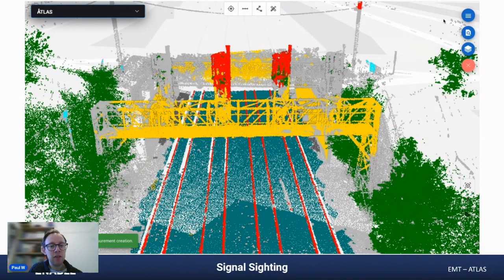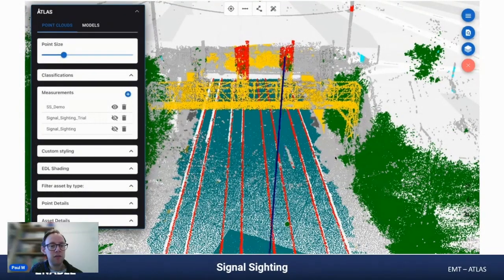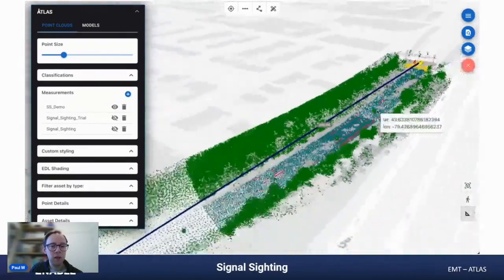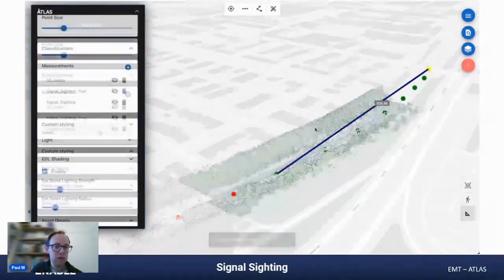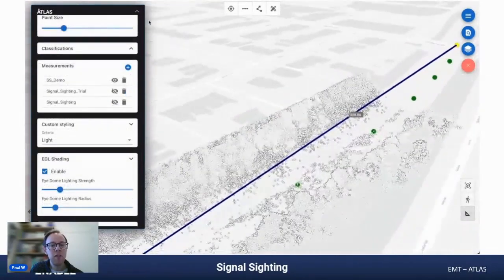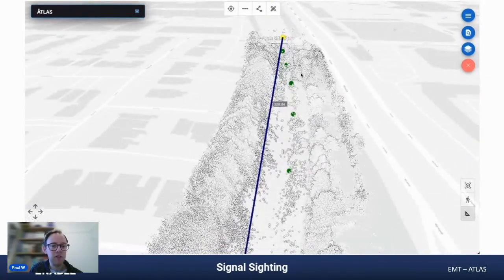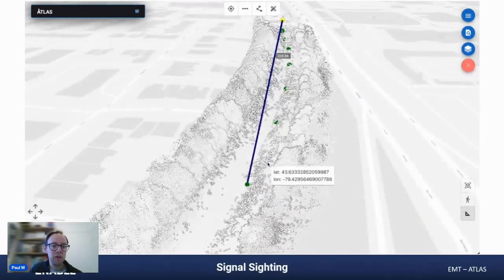After the calculations have been completed, the results are displayed, overlaid within the view. The maximum unobstructed line of sight is represented with a blue line, along with the source coordinates being color-coded, green for the unobstructed view and red for the obstructed view. Having this feature provides a quick and effective way to identify potential obstructions along the rail corridor, or to determine a maximum distance from which an object can be seen.